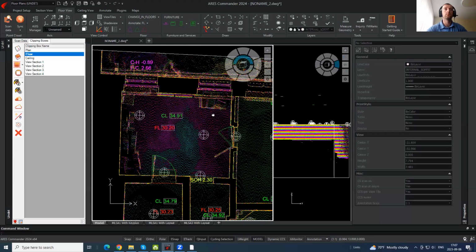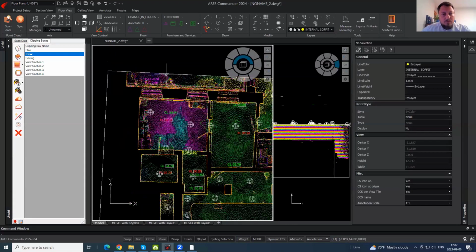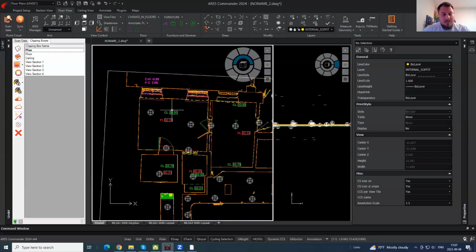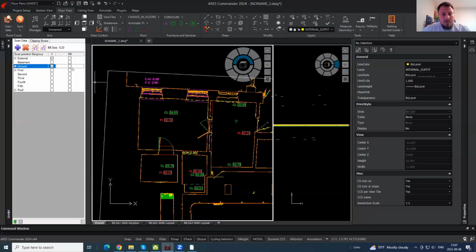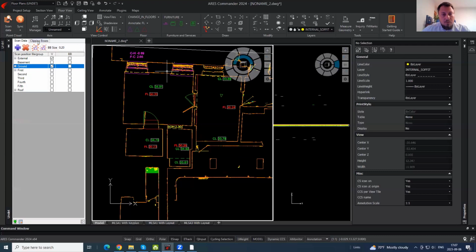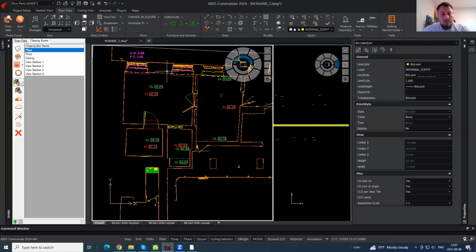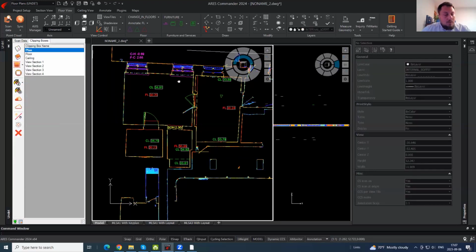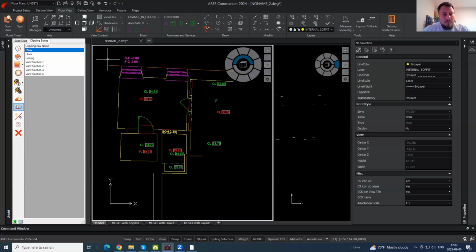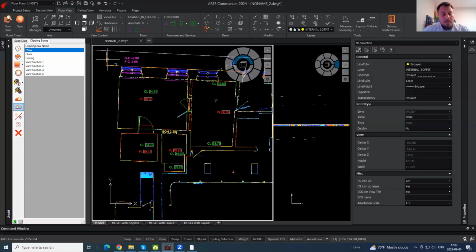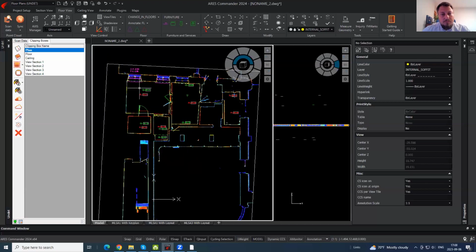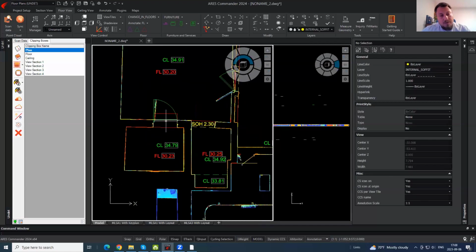Okay. I think that's all that we need to know about the workflow for the floor plans, because as you can see, we vectorized the main outlines of the building, of course only a small part of the drawing because it's a huge building, but the process is the same. Typically, we are slicing the point cloud, and first we extract the walls, internal and external.